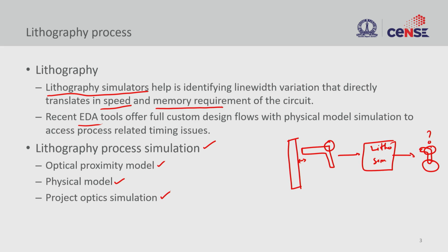And in advanced tools, you can actually extract all these defect points, or locations that you need to attend to, right. For instance, if there is a very narrow gap, and post simulation you find out that this gap would merge, creating a short circuit, you will go back to your design.